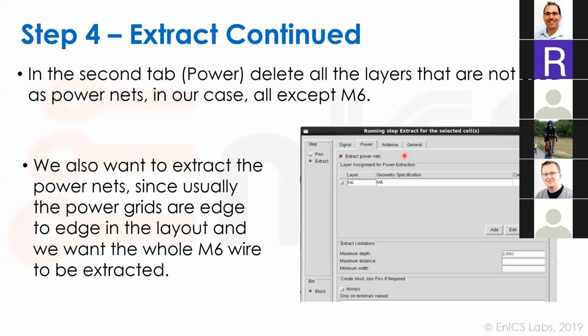This is just easier because most of the time the power nets are everything on metal 6, which is the power layer, I won't have anything but the power grids. So I don't mind doing extract for the power. Exactly. So that's the case you'd use it. You never want to extract anything that's not on one of these top layers, such as the signal pins, because this means that the tool will always do something wrong and it will start routing things through your macro and cause shorts, which it shouldn't do, but it will happen. Yeah. Okay.